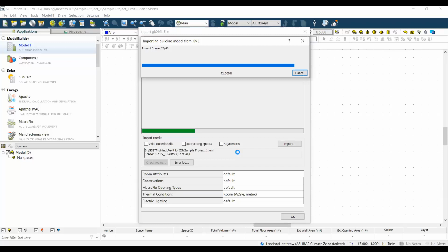This is what I'm talking about when we trace the outline of our roof for the sunshades. We aligned it to the center line of the walls. So as you can see, it's perfectly aligned to the boundary of the room element. Because if you have only traced until the exterior face of the wall, you might see a gap between these two.